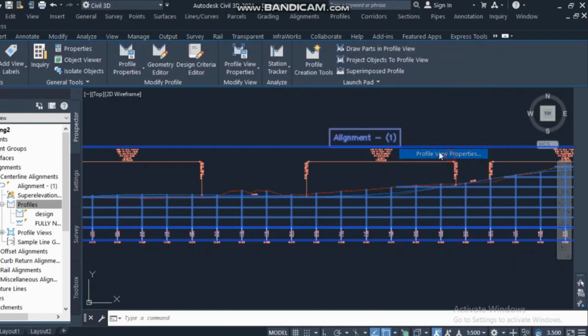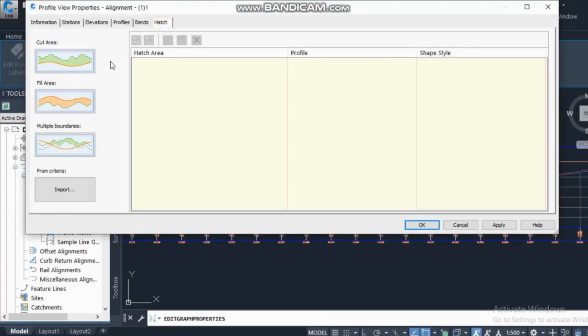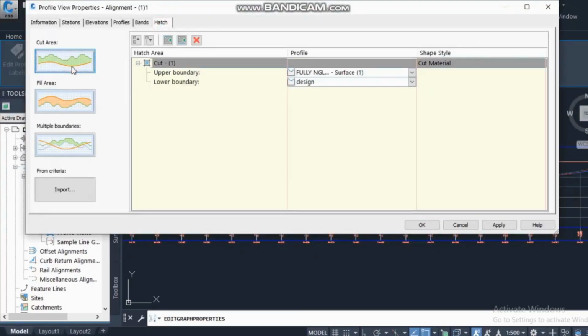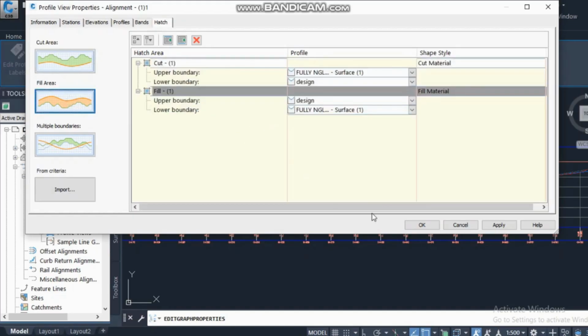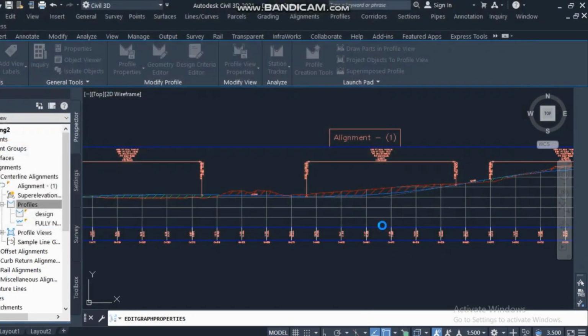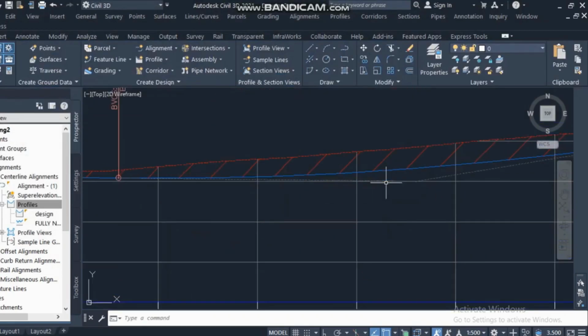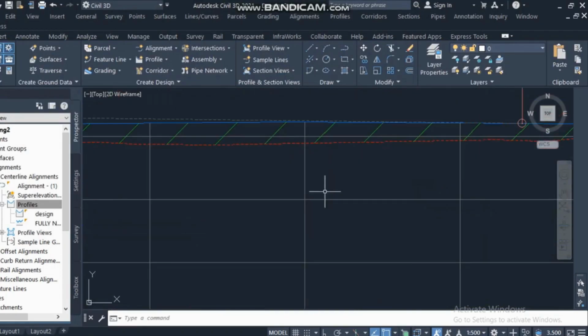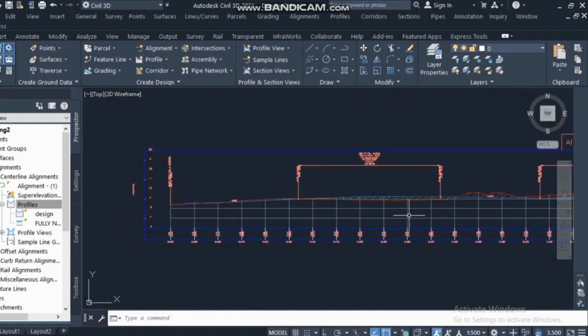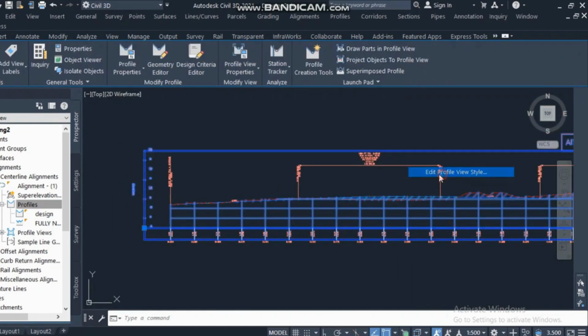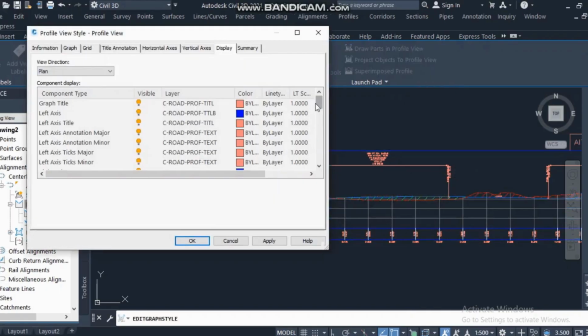So from the option, as we calculated yesterday when we were doing this from the H area, you can cut, and for the fill area you can specify the H area. If you click apply, the cut and the fill will appear here, the cut in one color and the fill in the other color. From here, if you want, you can turn off this appearance.